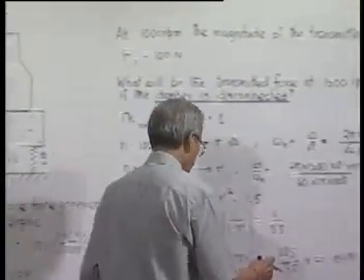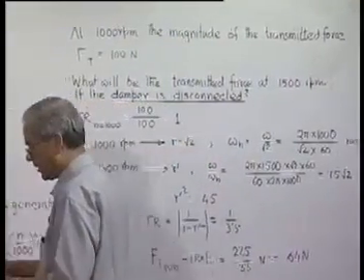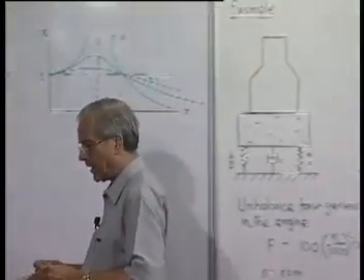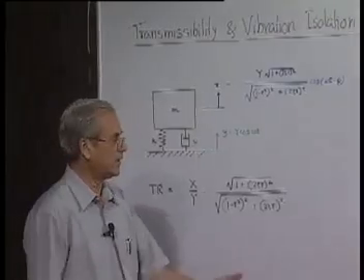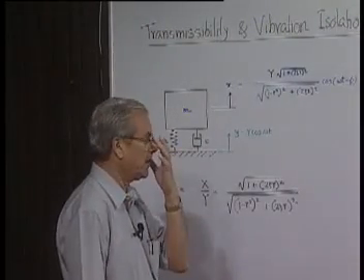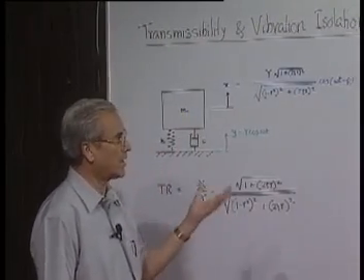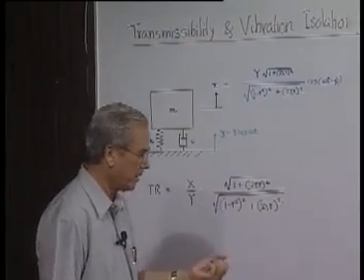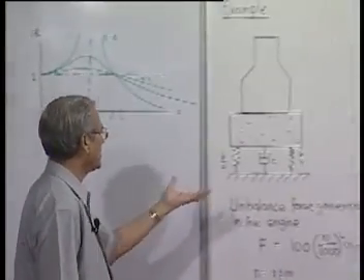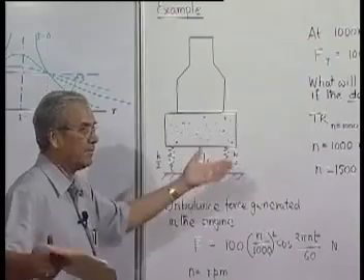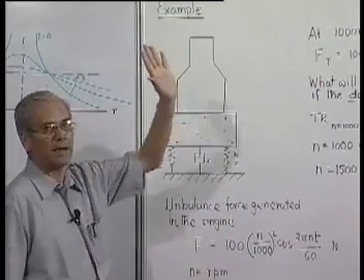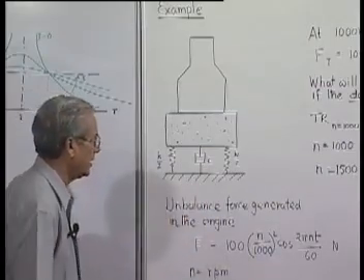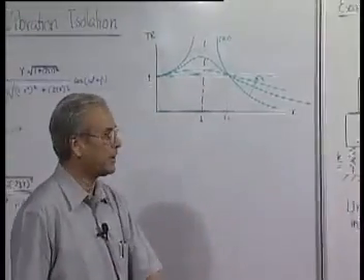So for simple situations, a designer should keep in mind not only the design of the machine, but the support system. In the market, there are standard isolators available, which are small systems which can be directly placed below a heavy machine which is being placed in a shop, so that the machine is isolated from the ground, not to disturb the ground.